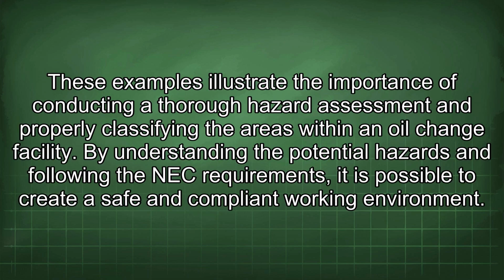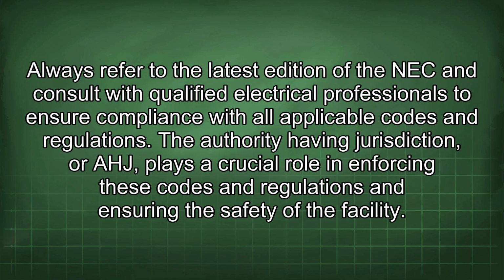These examples illustrate the importance of conducting a thorough hazard assessment and properly classifying the areas within an oil change facility. By understanding the potential hazards and following the NEC requirements, it is possible to create a safer and compliant working environment. Always refer to the latest edition of the NEC and consult with qualified electrical professionals to ensure compliance with all applicable codes and regulations.